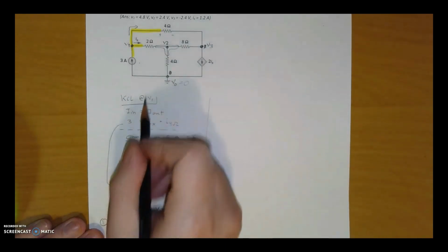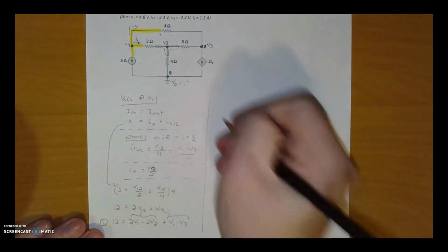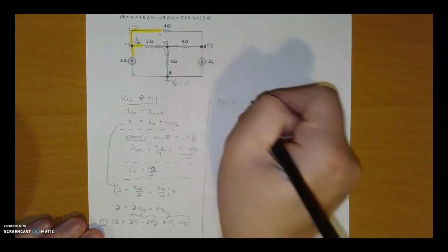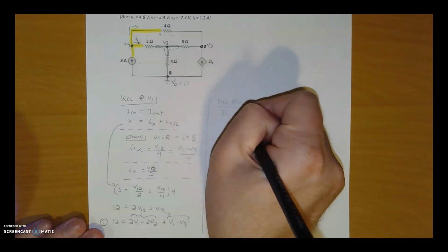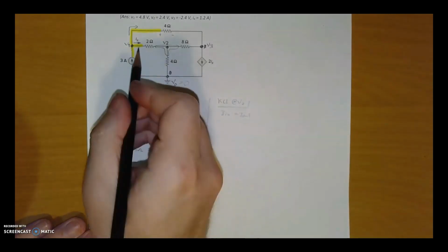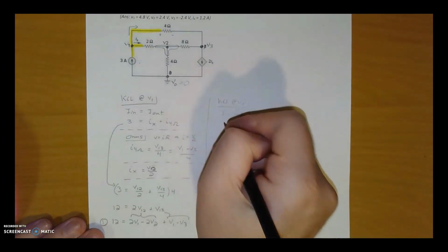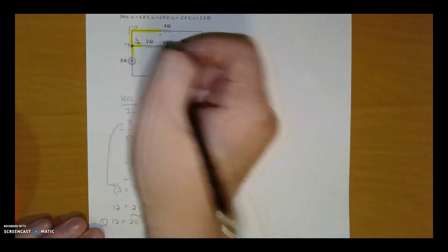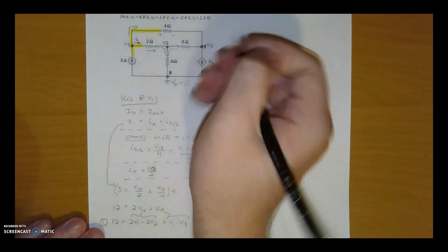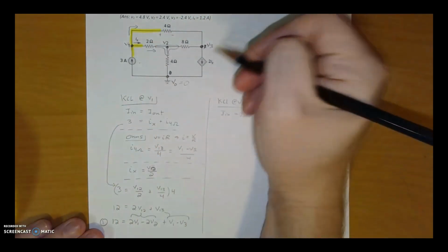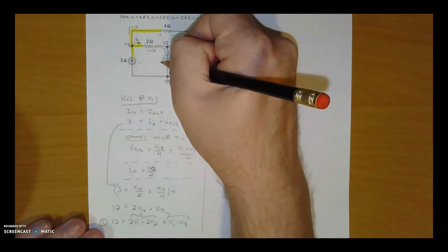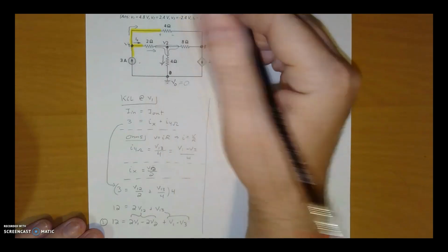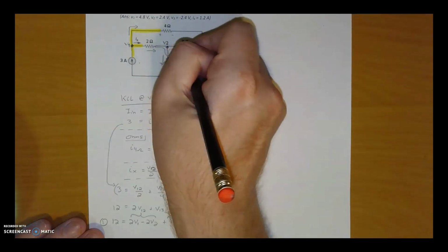So I've already done a KCL at V1, so I'll just move over and do a KCL at V2. All right, and this is I in equal to I out. So going in, I have this IX, but again, I don't want to call it IX, so I'm just going to go ahead and call this the voltage. So again, if you want to, go ahead and label your directions. It'll help you at the beginning. A hint is if you have a ground, make your currents go towards the ground. Otherwise, you're going to get some weird negatives. You'll be able to handle it, but it can just make things a little difficult.